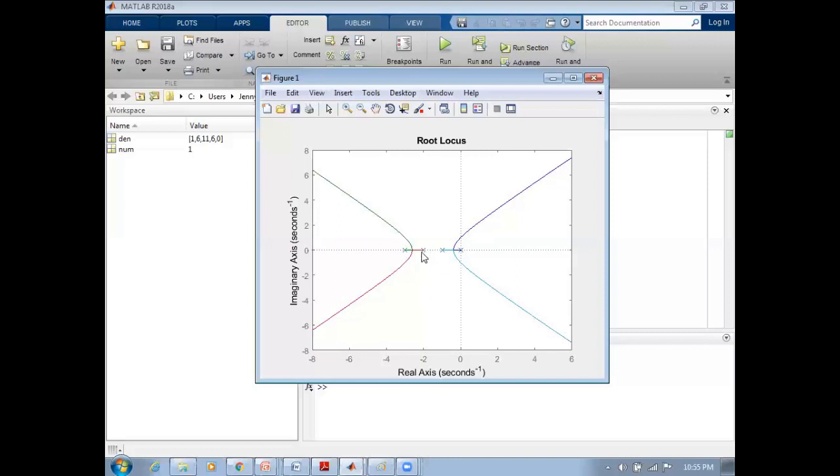Similarly, for s equal to -2, when k increases, it reaches one point, and on the other side, when s is equal to -3, at k equal to 0, it increases, and both intersect at one particular point, reaching the breakaway point. Then this breaks away and tries to reach infinity. And on the other side, this branch is trying to break away and reach infinity.